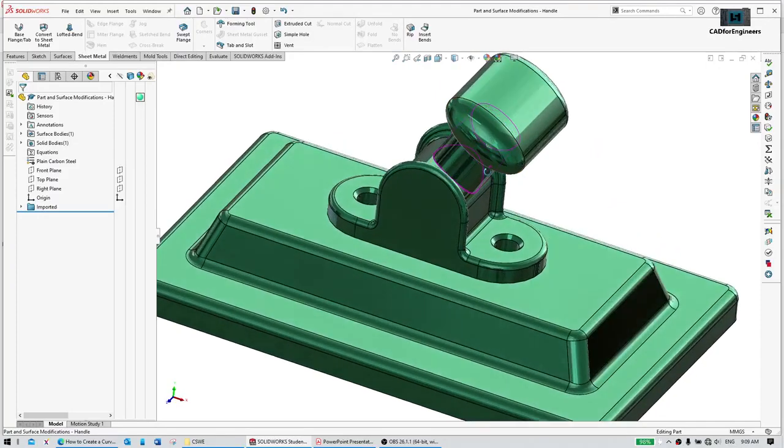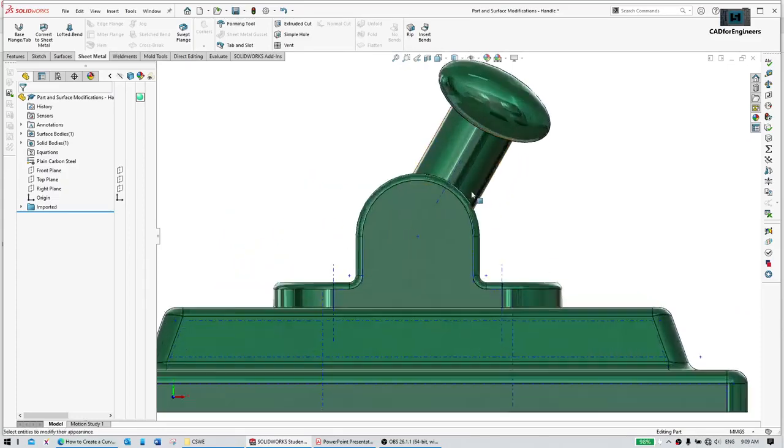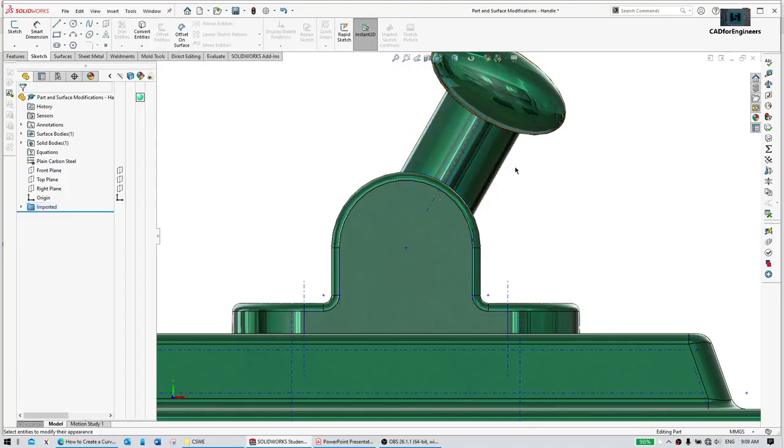The first, what can I tell you? You should be able to know about, let me go ahead and check the eyeball. Over here, under the eyeball, we have a couple of views that we can manage. Let's say first, this temporary axis. If I turn on the temporary axis, I'll have this axis, which allows me to measure the angle between this line and this line, right? Or I can draw the line as well, or in the sketch, I forgot actually, the intersection curve. Using the intersection curve command, I can get the projection of this edge, and then I can find the angle between the edge and also this surface. So it's a pretty easy task.